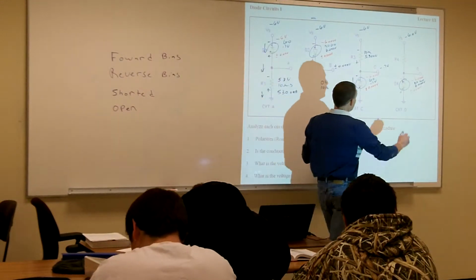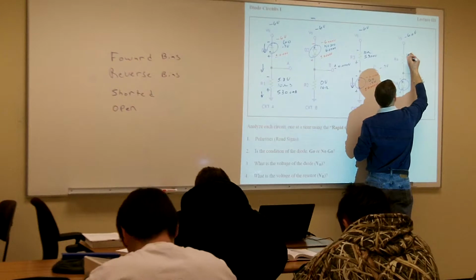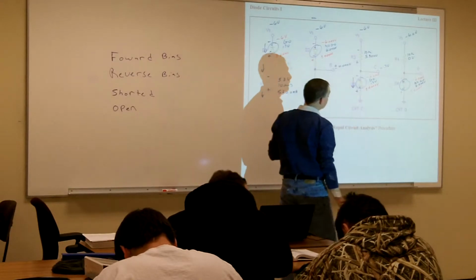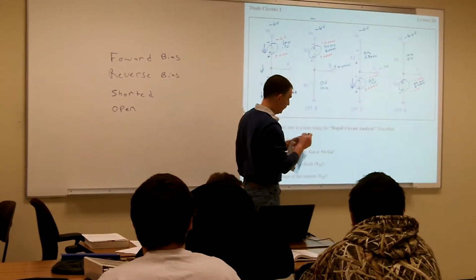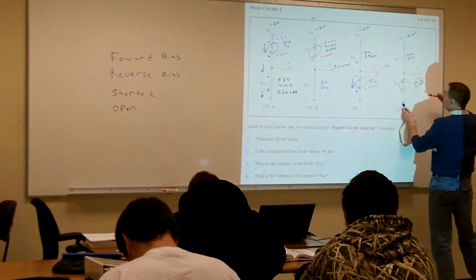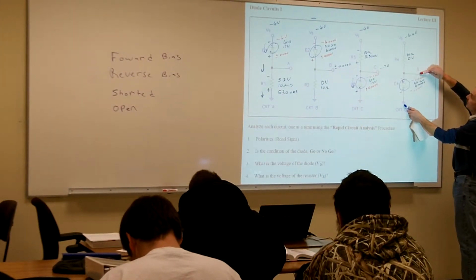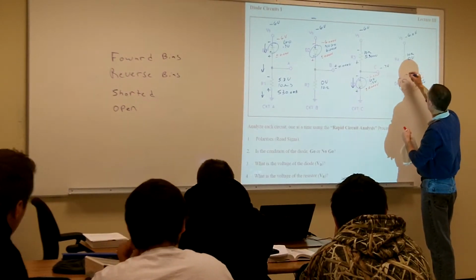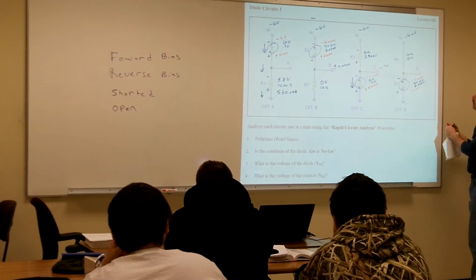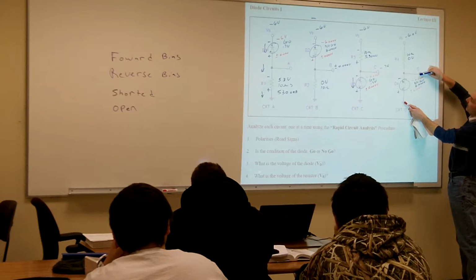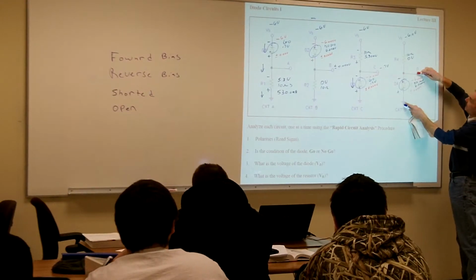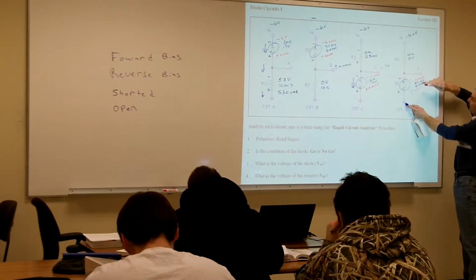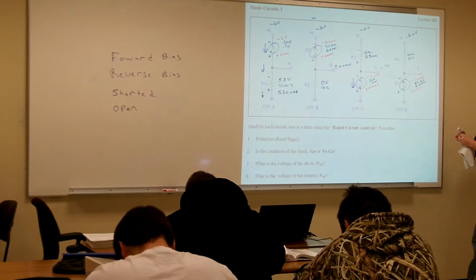Okay. Then the voltage going across my R4 then? 0. My voltage at my test point? 0. Yeah. These aren't soft, the reds are soft voltages. The blues are the hard voltages now. So what's my polarity across my diode? Bring my red lead down to my black lead. What's the first sign I see? Negative. But my voltage drop is 6 volts, so I'm going to get a negative 6 volts.